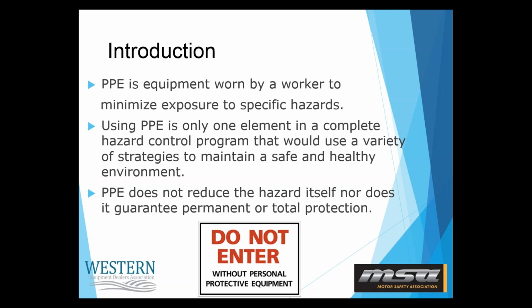If we were sitting together in our service facility and we have an air compressor that's putting out 100 decibels of noise, and if I asked workers to wear hearing protection, I have not done anything to address that hazard right at the source. So just relying on hearing protection to keep my workers safe is part of the control, but dealing with that item at the source is more important. And we'll touch on that hierarchy of controls shortly.